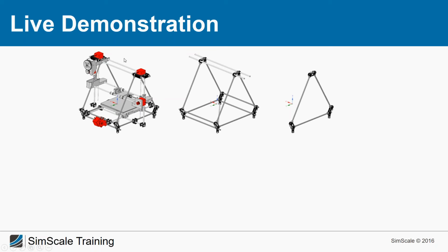If you now take a look at the whole printer and then at the frame, you can see here in red all the stepper motors. And the stepper motors in the end are moving with a defined frequency. A very big problem in manufacturing, not only for 3D printing but also for milling, is that vibrations can result in a worse product quality.